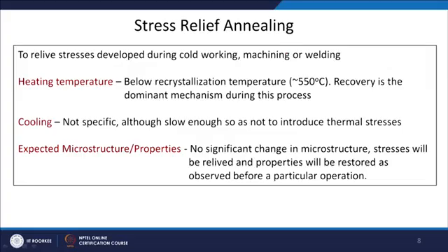So, we have to do a stress relieving operation, to relieve stresses developed during cold working, during any forming, let us say rolling operation or extrusion operation. Any cold working, machining or welding processes, whatever stresses you develop, can be relieved by doing a stress relief annealing.